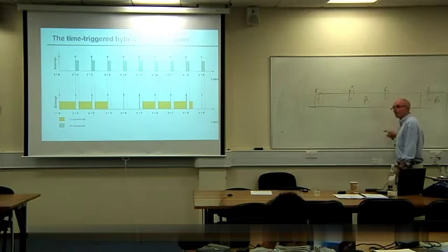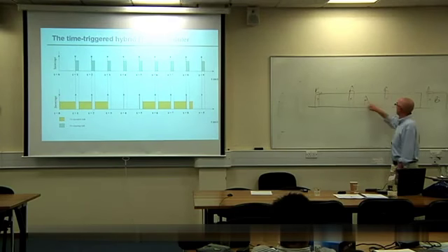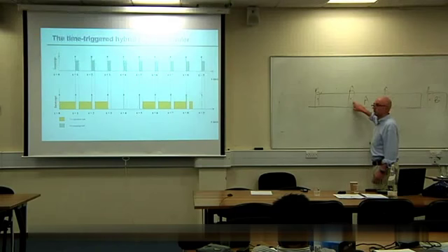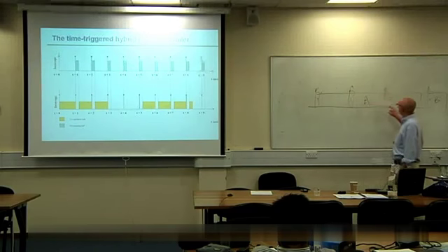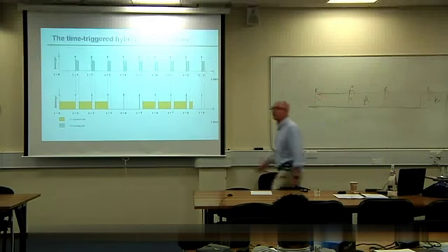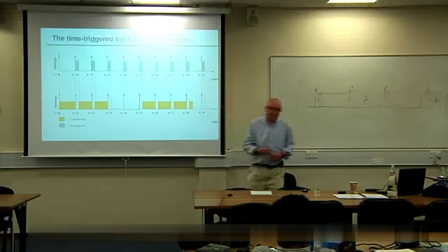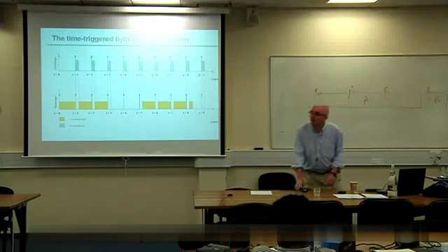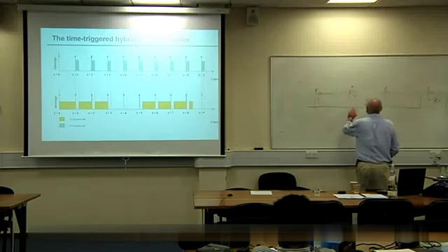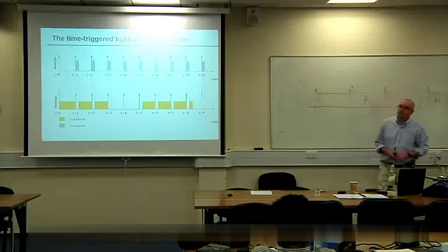We could do that, or suppose that task runs for a second, and we've got an emergency stop button that we need to check every 50 milliseconds or so. Check the emergency stop button in this preempting task, and you'll make it run quite happily. That's what a time-triggered hybrid scheduler does. So it's a very simple way of introducing task preemption into your system.